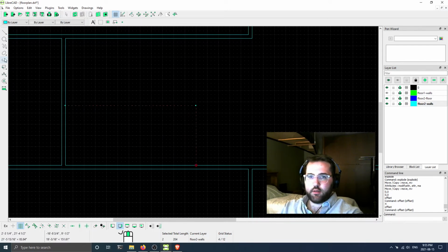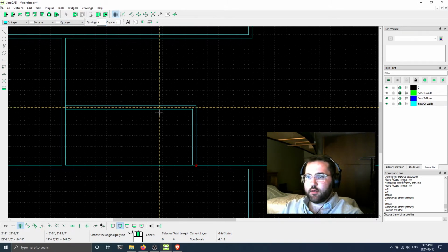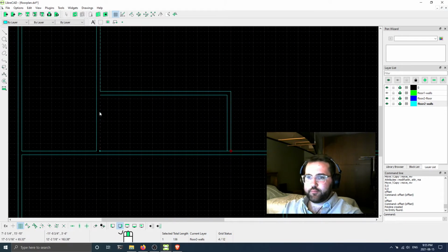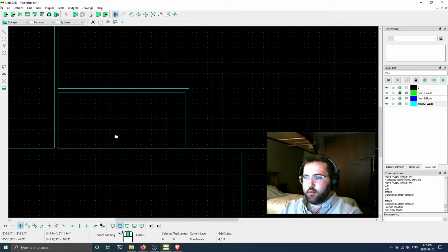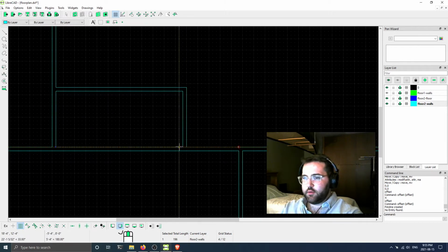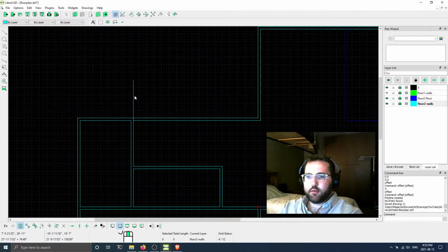Now I'm actually going to make this a polyline, and I'm going to create equidistant polyline. Did before, and set it to 4 inches, and click over like that. And then just the same process as before. Dragging 2 points around, bring that over like that, bring that over like that, close that up, and yeah, gotta drag that line back in there. I don't know how that happened.